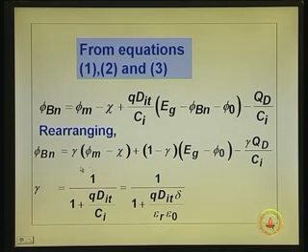Now, gamma is related to the interface state density dit. If dit is 0, that term goes off and you have gamma equal to 1. With gamma equal to 1, this term goes off, and you will have only the small term coming up. So, mostly phi Bn will be equal to phi minus chi when gamma equal to 1, that is when dit equal to 0 and also delta equal to 0. Both the terms will go off, ideal. That is the ideal situation.